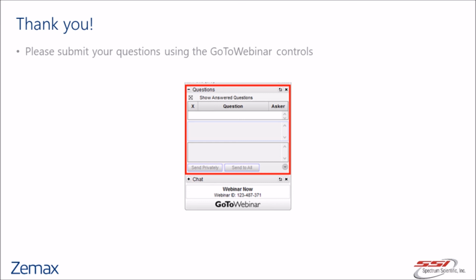So the higher order Zernike terms like rho to the 8th, rho to the 10th, rho to the 12th start to look like rotationally symmetric ripple. So you can use those. You could use the Zernike surface to put that kind of ripple into your system if you want to.